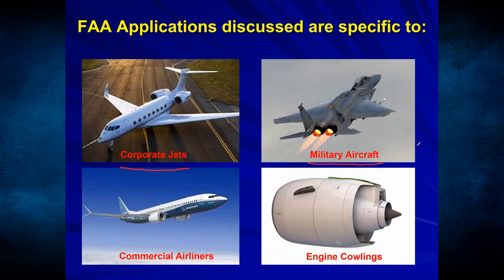And as a U.S. Air Force veteran, this is an aircraft that I worked on a lot in the Air Force. And we inspected wing tips, flight controls, the vertical and horizontal stabilizers there. Those are composite structures, even this area of the canopy, and also some areas of the intake. So pretty much, I'd say like 70% of this aircraft is composite. And a lot of corporate jets are composite too, which is why NDT inspection is so important for these aircraft.